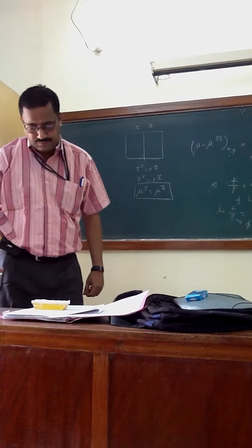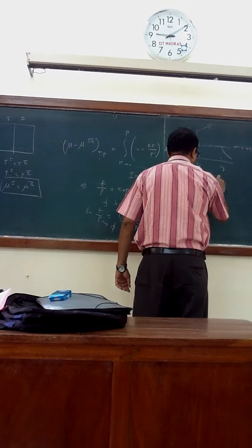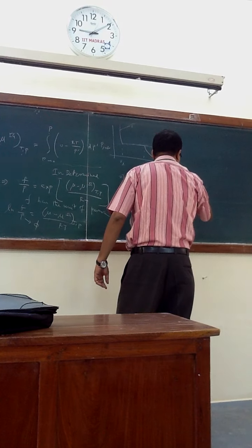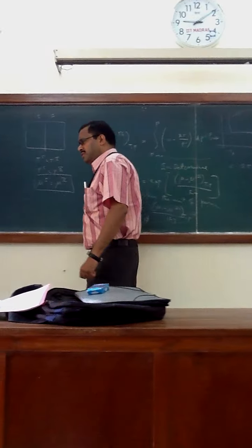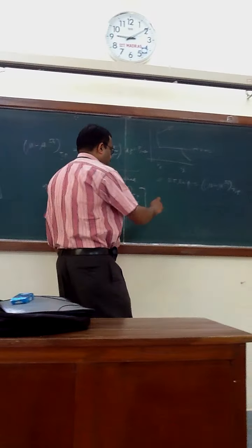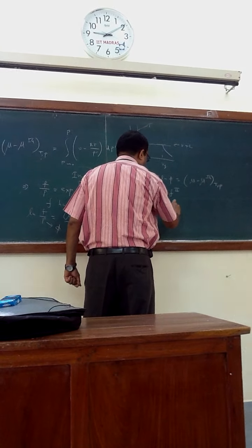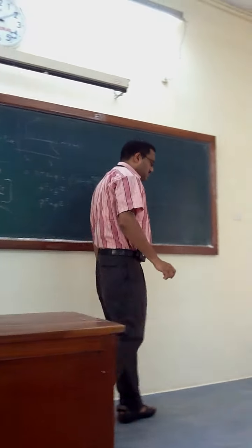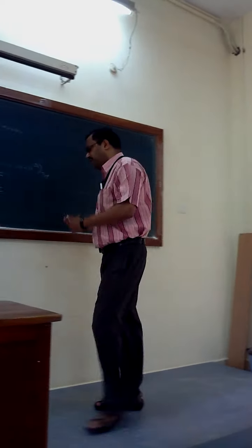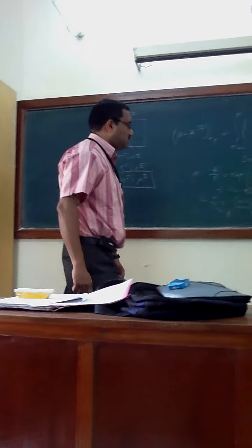So this much we have learned. RT ln phi is nothing but the departure of chemical potential. And then, starting from mu1 equals mu2, we derived f1 equals f2, and we derived phi1 equals phi2. Both are valid here because of pure phase, a pure substance. For multi-component substances we will have different considerations, which will be discussed later on.